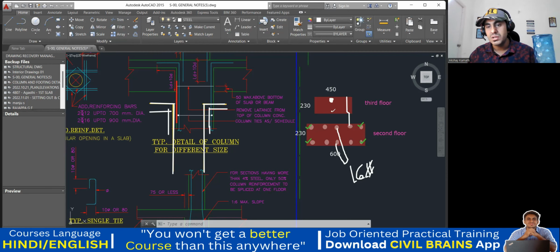This bar and this bar, you don't require it to be 16 diameter. I want that to be a 12 diameter. So in that case, what will you do? You have two options. Again, if you don't require these two bars to be taken here, then you can do the lapping. This 12 diameter bar will look something like this.